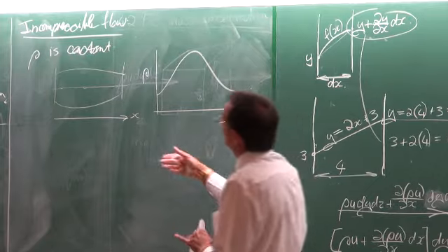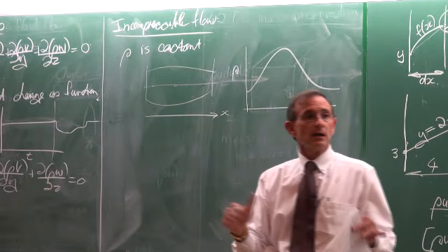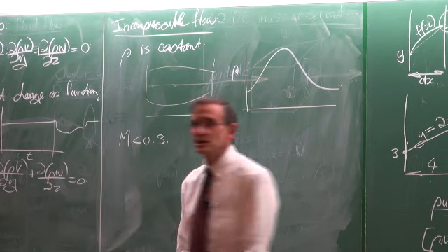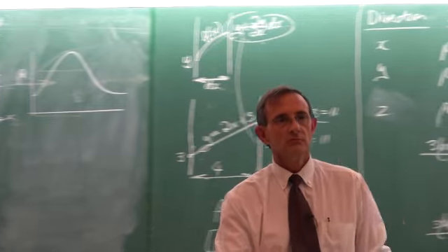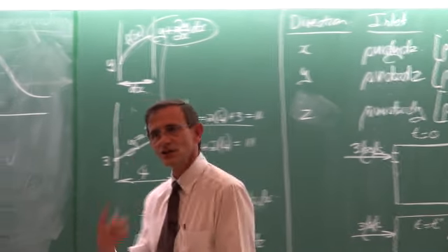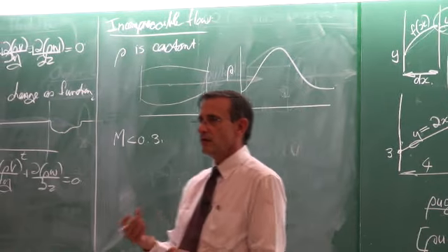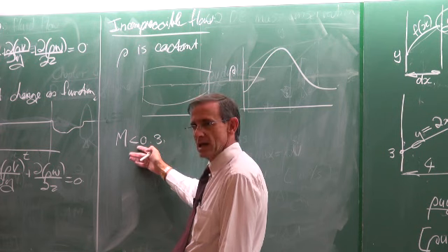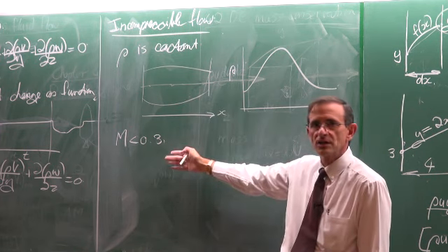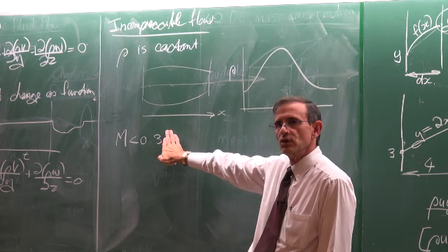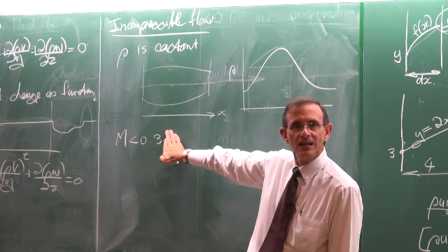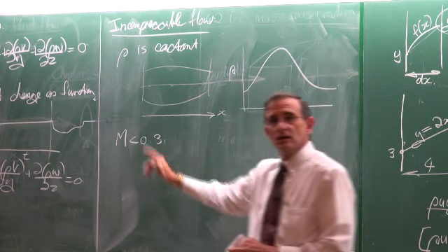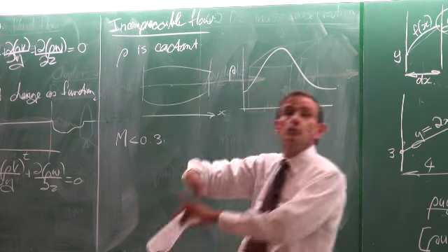But if the Airbus is flying at a Mach number smaller than 0.3, and we are interested in the airflow around it, then we can make the assumption that the density is constant. Air is a wonderful fluid for us as engineers. The Mach number is an indication of compressibility in fluid mechanics. And from experiments we know that if the Mach number is smaller than 0.3, then the density changes are negligible. But that would now not be through the engine, it would be on the outside.